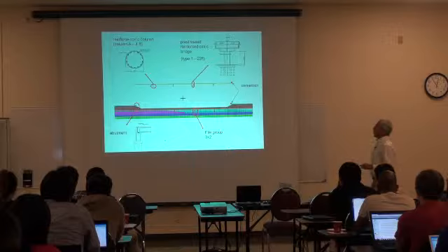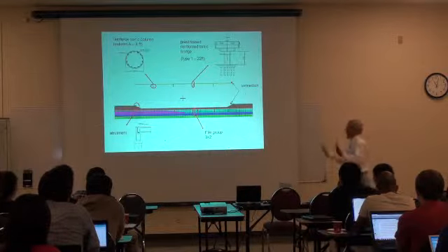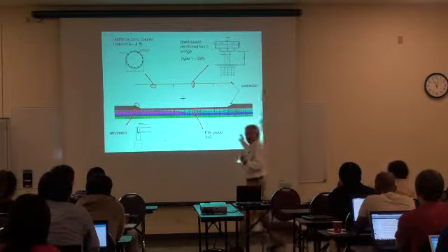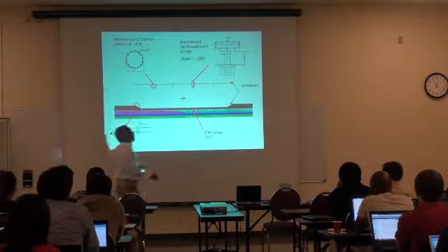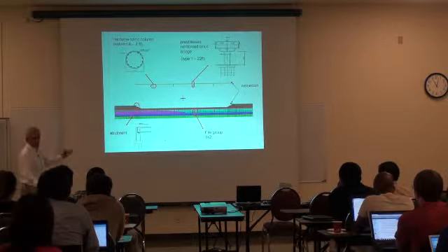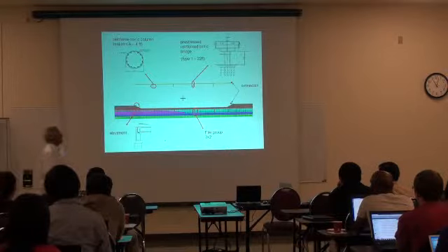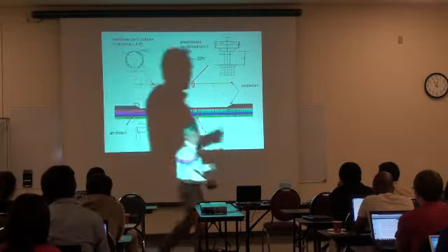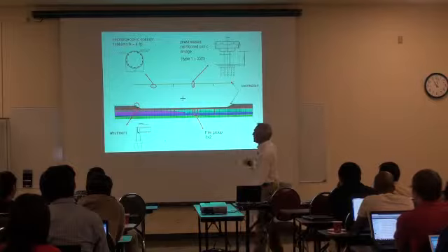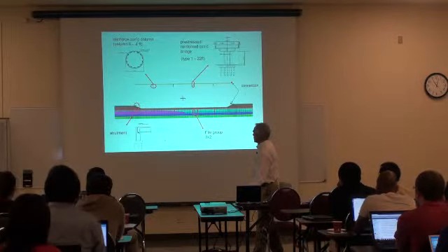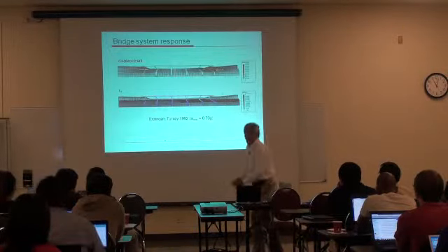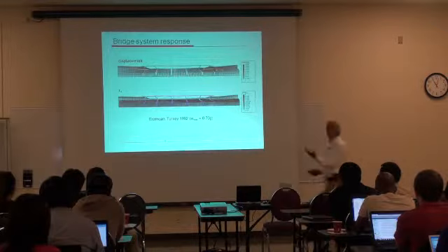And again, look at the mesh. Very coarse mesh, bad mesh. Not the best one that we could have. But it was a compromise. I had to run thousands of these cases. I could not do that using a much more refined model. I was not using parallel OpenSees at that time, and I had real limitations. So now we use that, and we obtained some very good results.